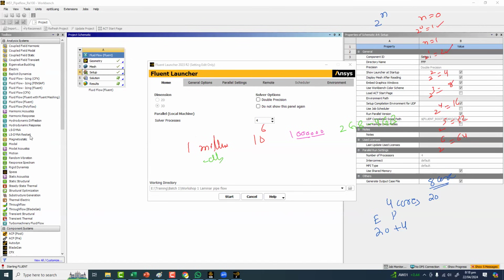And then we also have a rule of thumb for the number of cores. For 512K cells, that is about 500,000, we at least need 1 core. If you have more cores, then you can go to 256K cells, which is a quarter of a million.